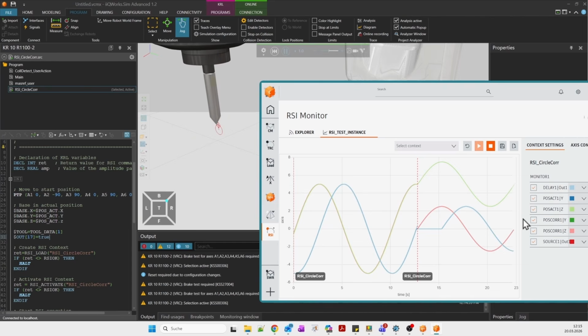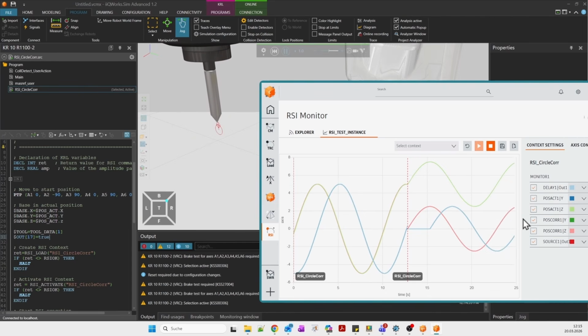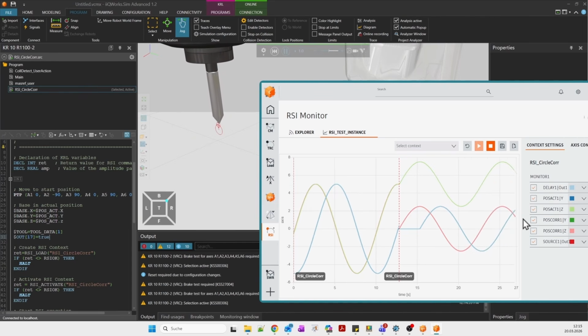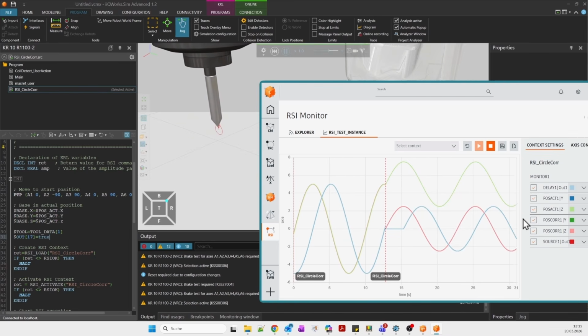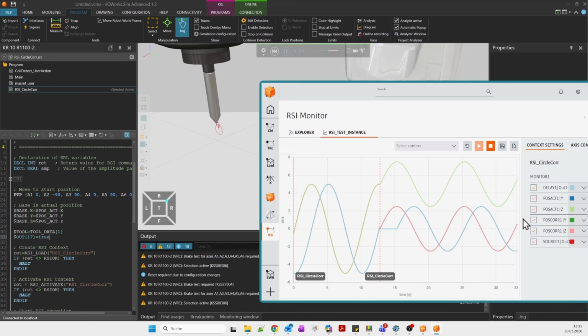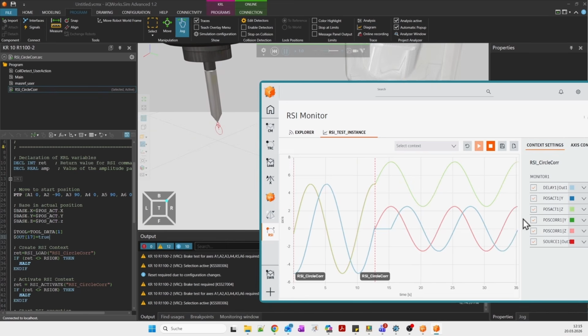The robot is controlled purely by means of corrections on the basis of the absolute correction values in the y and z directions. After a defined time, the sensor-guided motion is aborted by means of a timer. This confirms that the sensor-based correction is active and working as expected. This concludes the first showcase of an example from the Robot Sensor Interface in iiQWorks.Sim using iiQKA OS2. The same workflow can later be applied to a real robot controller.